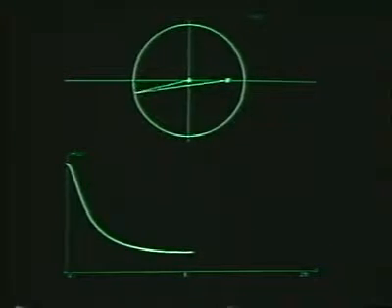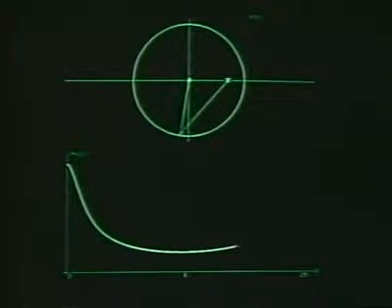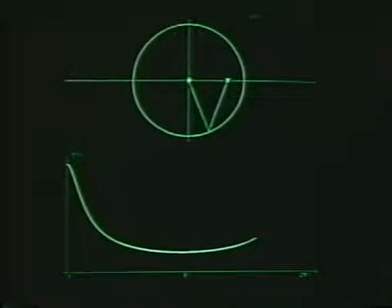And so now the pole vector begins to decrease in length, and correspondingly the magnitude of the Fourier transform will increase, and that will continue until we get around to omega equal to 2 pi, which is equivalent, of course, to omega equal to 0. And obviously, if we continued to sweep around again, we would simply trace out other periods associated with the Fourier transform.